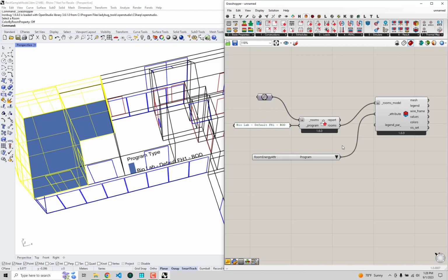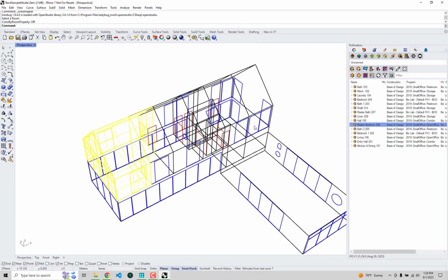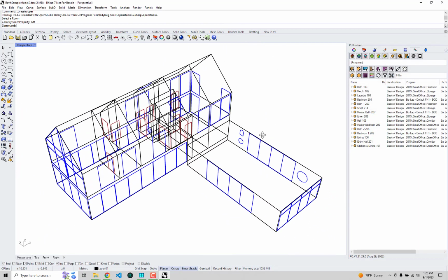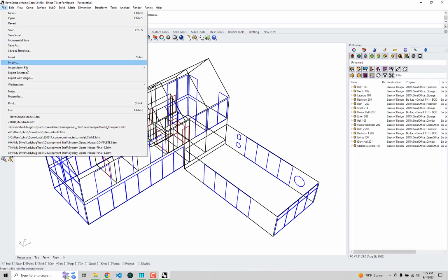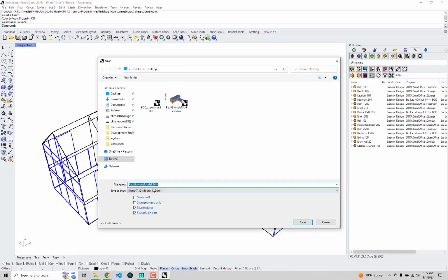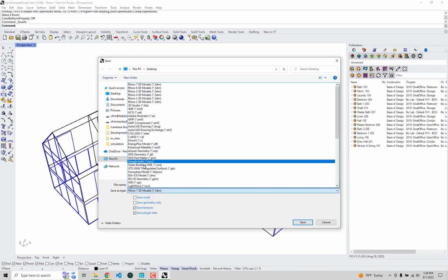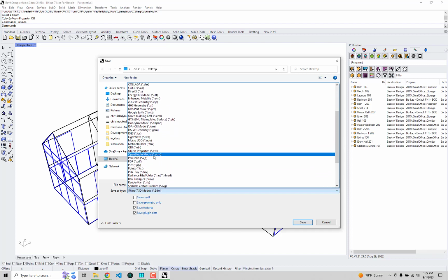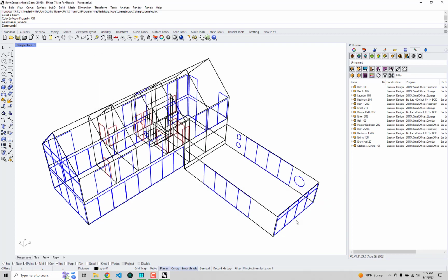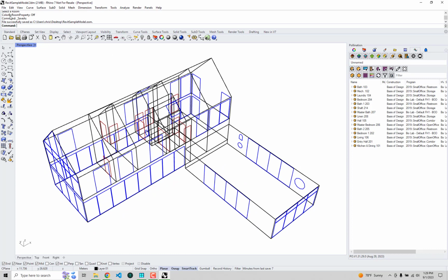Maybe I'll just show you one more capability quickly of this. I'm just going to X out of this Grasshopper window here. But I just want to show you guys quickly when you save these, let's say I save this model to an OSM, this little sample model, a Revit sample model here. I'm just going to go over to our Save As menu, and if I have the Pollination Rhino plugin, I can just select Open Studio Model. Now let's save this to my desktop here and give this a second. Okay, so that took a few seconds, but it said file successfully saved to an OSM.